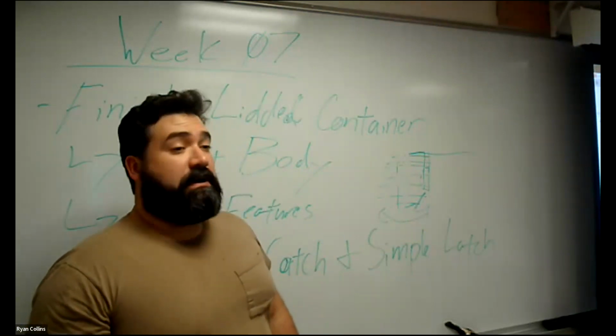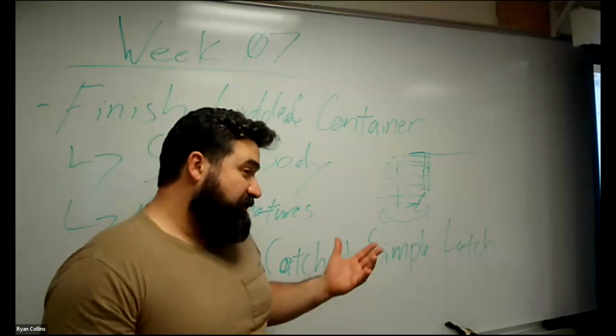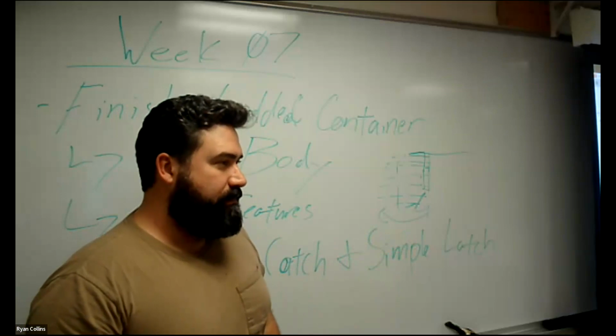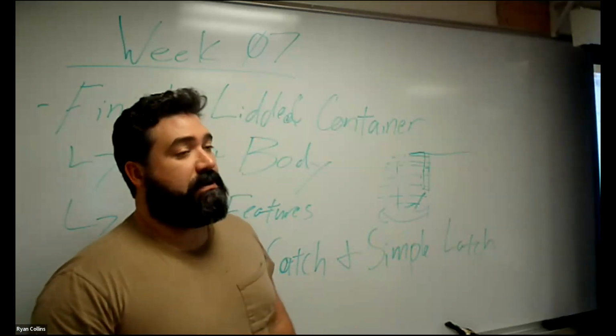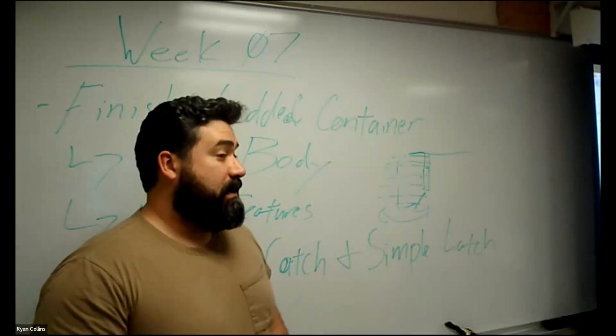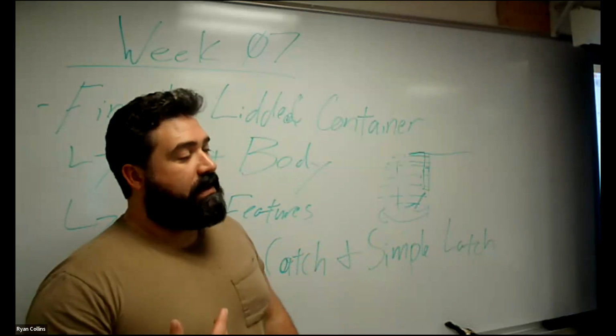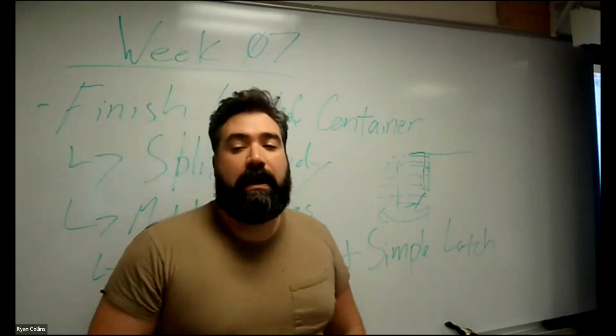The other thing, be cautious of what material you use. PLA is fairly strong. It prints nice and clean, but remember, it's a little bit more brittle because of the nature of the material, and it prints at a lower temperature. PET is a true plastic, so it has the benefit of being a little more flexible, and it bonds better because it prints at a higher temperature, also because it's a polymer.